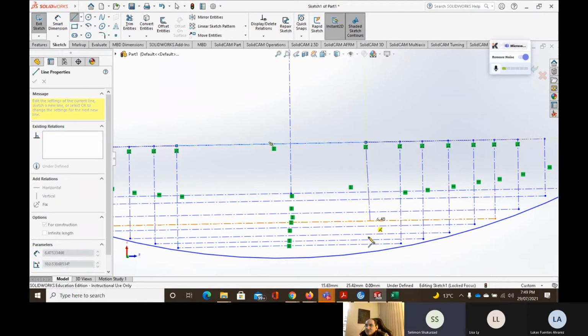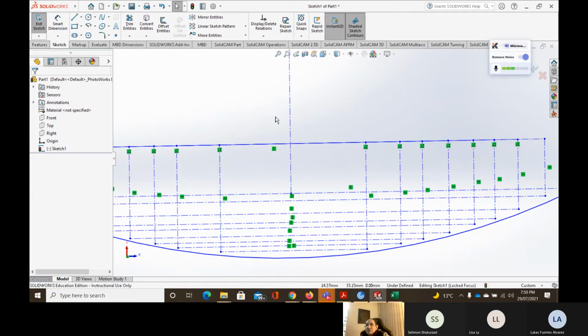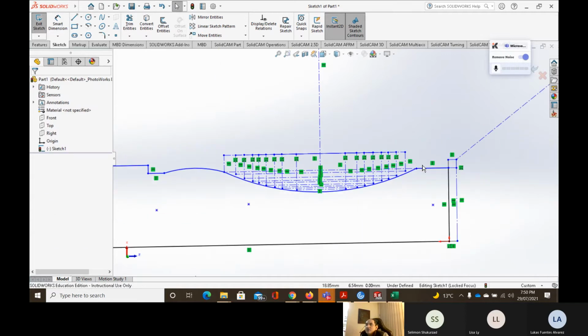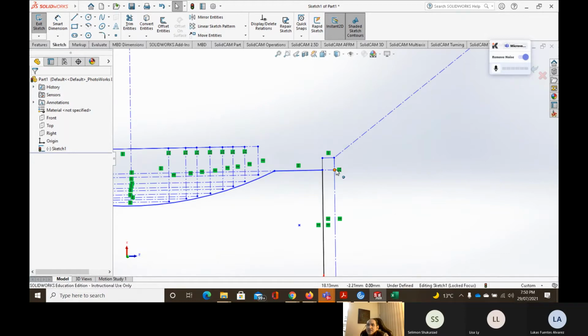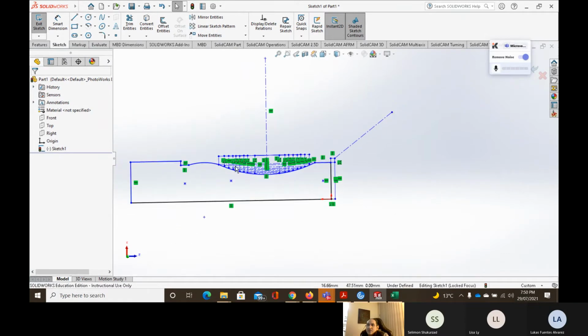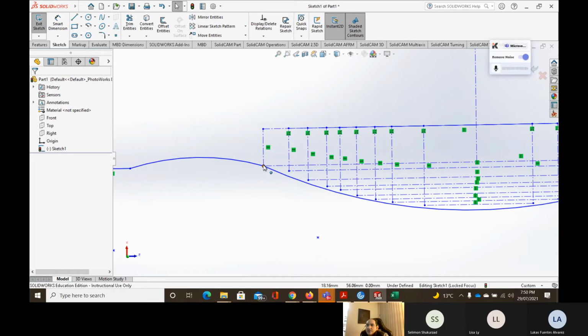Okay, so these will be the multiple steps we're going to cut. We're going to have something like a spherical shape, and the rest of the material is going to be removed by the last cut, which is going to be the G02. So now to explain the process once again, we come to here, G00, G01, G01, G00, G00. Or I can come to here directly, then G01 to that point.